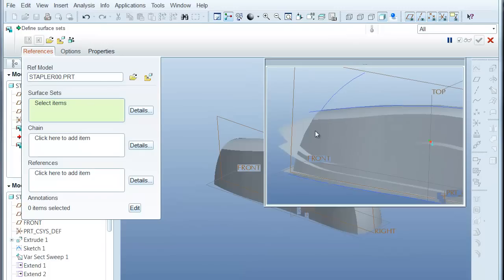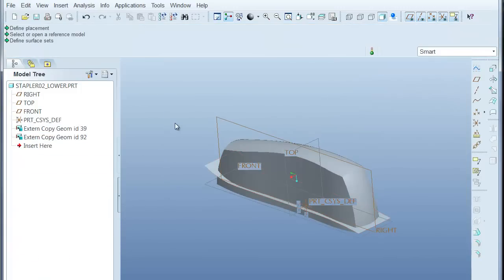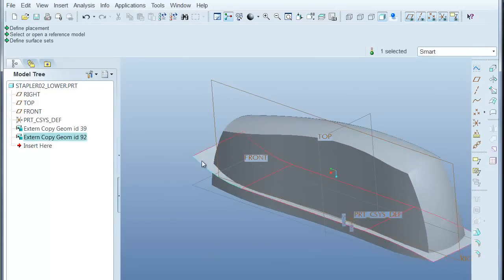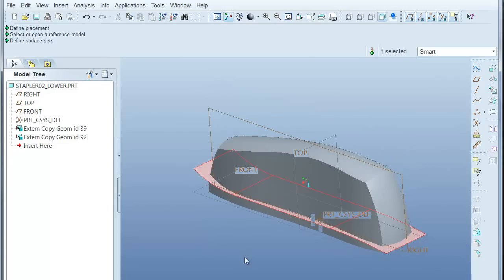Okay, I'm going to grab the lower geometry, right click through to get the entire quilt, and left click on that. I do that because I'm trying to make this geometry so robust that somebody might come in and take it. See how it's built in 3 separate panels? That's a straight line and 2 arcs on either end extruded from that. Somebody might turn that into 4 or 2 geometries, and I don't want this feature to fail because of that.